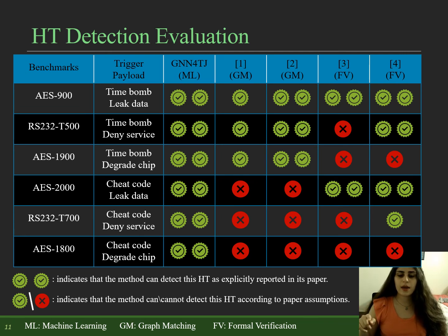So in their papers, they haven't looked into the last 3 types of Trojans, so they can only detect the first 3. The last 2 designs are based on formal verification methods. This technique tries to define a property for the Trojan, and they detect the Trojans that satisfy that property. For example, the third design just detects the Trojans that leak information.